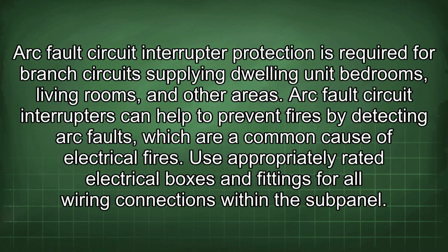Arc fault circuit interrupter protection is required for branch circuits supplying dwelling unit bedrooms, living rooms, and other areas. Arc fault circuit interrupters can help to prevent fires by detecting arc faults, which are a common cause of electrical fires. Use appropriately rated electrical boxes and fittings for all wiring connections within the subpanel.